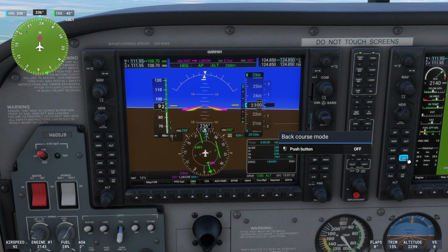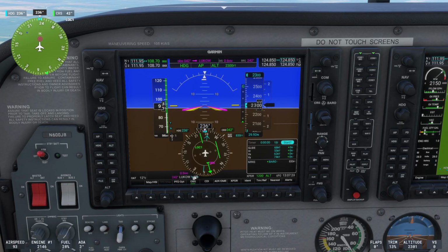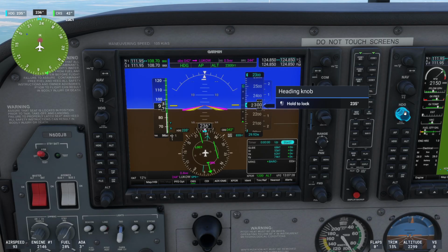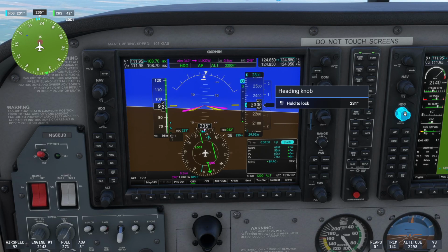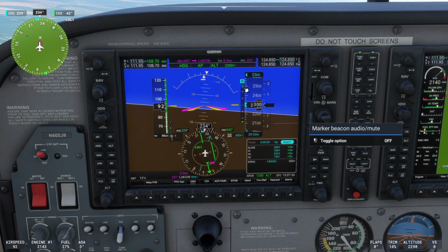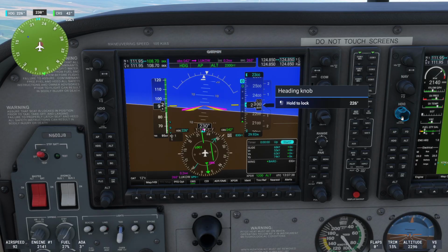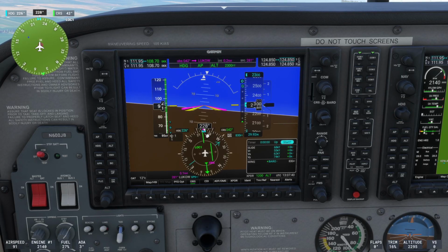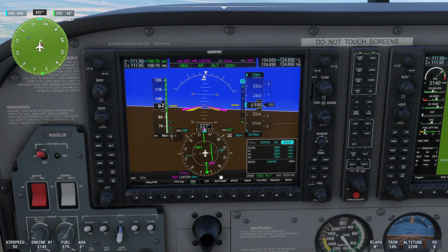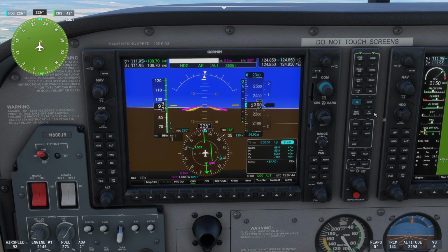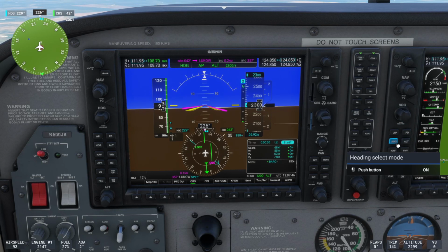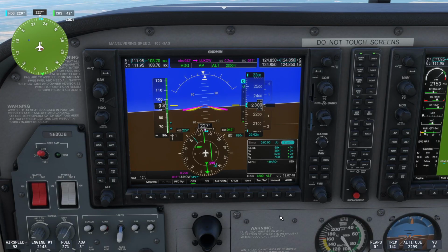Right, now approaching Lookout, we'll start to see this distance going down. We're at 0.5 miles away. That blue RMI needle is going to want to start flipping around as we pass that waypoint. And of course that localizer course is going to start coming in, as well as the outer marker is going to start beeping again. So we have a lot of different ways to know that we're at Lookout. It's just getting there, we're using GPS. So from there I'm going to do this parallel entry, and then I'll show you what it's going to look like on the way in.